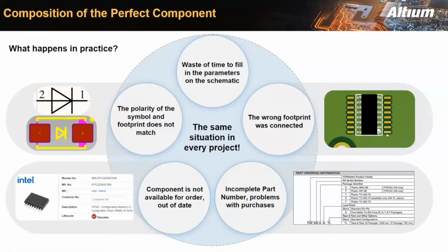Also, another common mistake is the name of the component, such as an IC missing the suffix code that indicates the package type. From the point of view of the circuit designer, there is no difference in the symbol, but from the perspective of PCB design and purchasing, the suffix that defines the package type is critical. Fortunately, the procurement department will technically ask which one to buy, but sometimes they don't inquire.